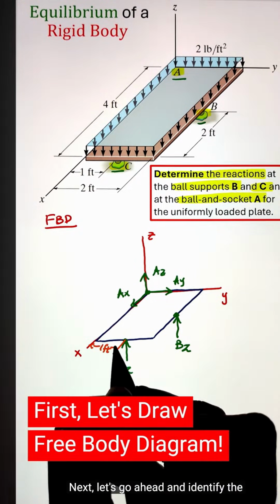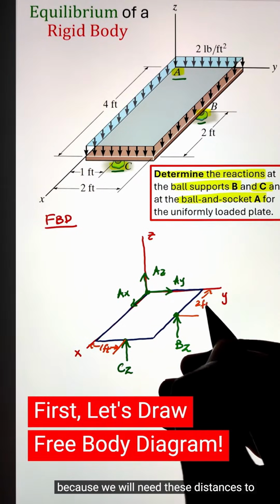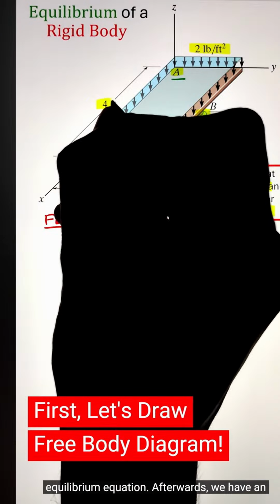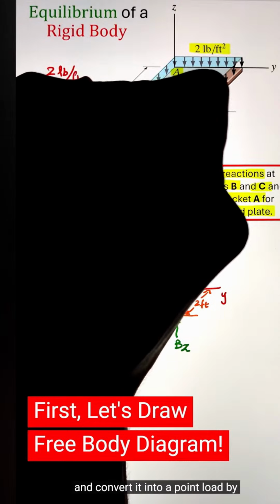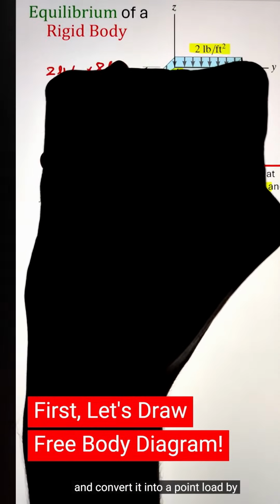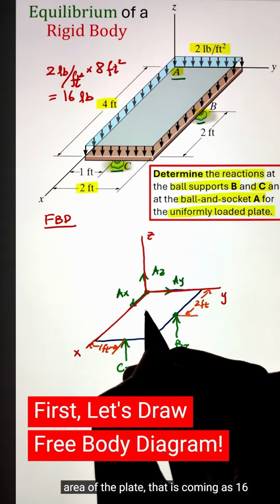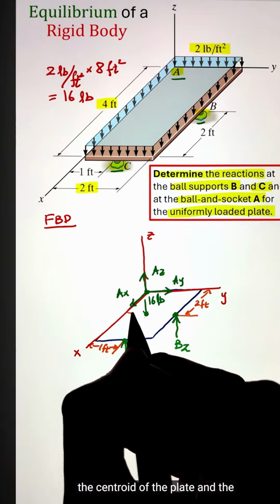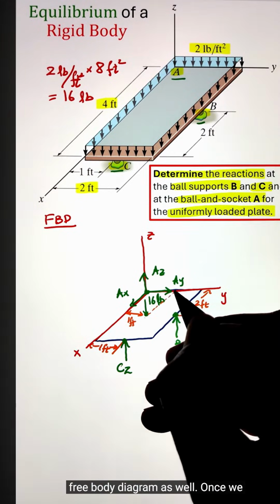Next, let's go ahead and identify the position of these support reactions because we will need these distances to calculate the moment while writing our equilibrium equations. Afterwards, we have an external load that is uniformly distributed on the plate. Let's convert it into a point load by multiplying that distributed load with the area of the plate, which comes to 16 pounds. Now this point load will act at the centroid of the plate, and we can list the dimensions on the free body diagram as well.